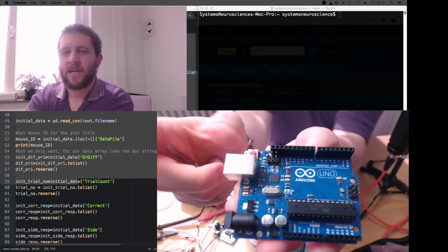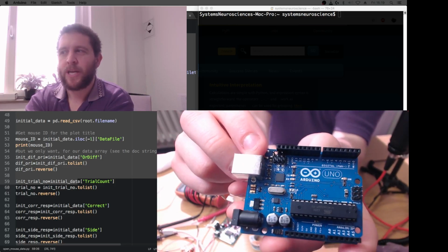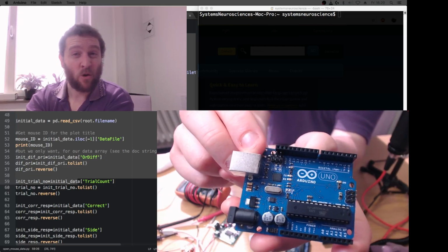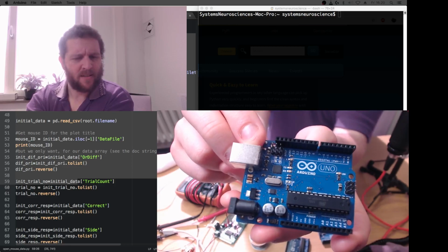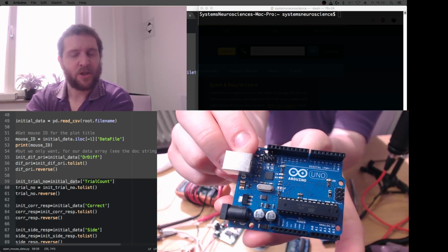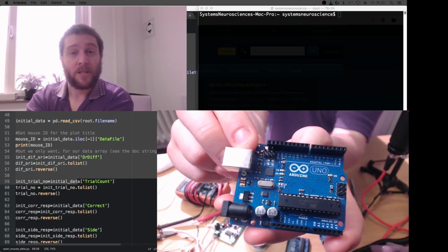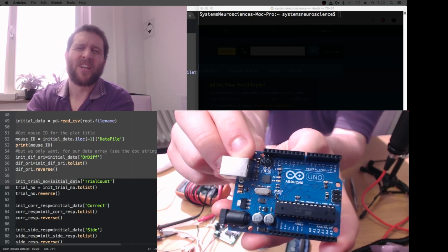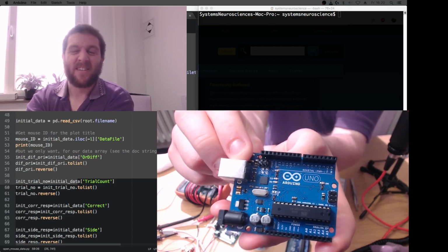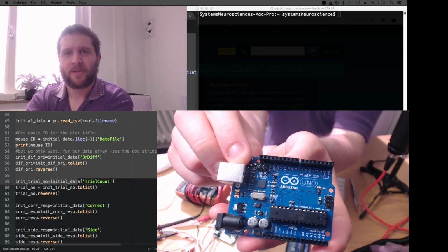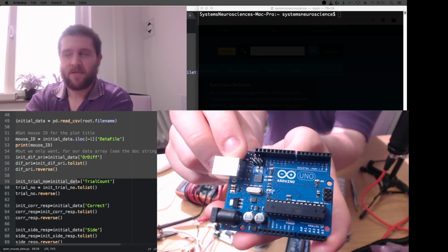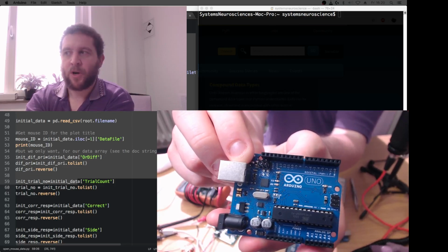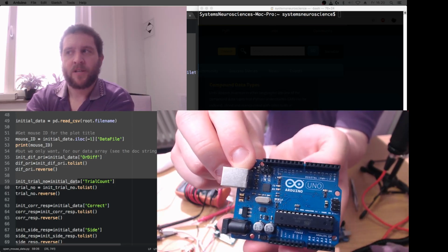You'll see down here where my finger is some analog in, A0 to A5. Arduino can also accept analog voltages. I think it's up to about 5 volts or 10 volts or something; I'd have to check that. It will accept any voltage up to the reasonable input, and it will undergo what's called an analog digital conversion, and the Arduino will convert it into a digital representation according to the bit depth, or the resolution of the ADC. Don't worry about that too much. We're not going to use these guys. We're going to use these guys up here.